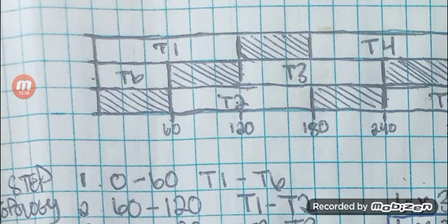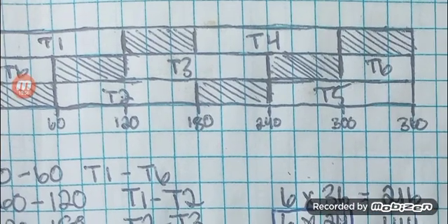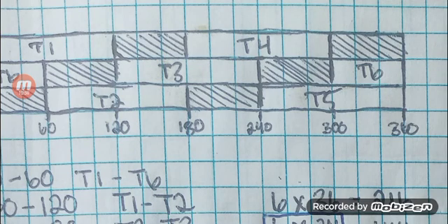And T2 turns off, T3 stays on, T4 comes on until 240 degrees, and then T3 turns off, T5 turns on till 300 degrees, then T4 turns off, and then T5 stays on, T6 comes on till 360 degrees, and it starts over. And that's per cycle, per 360 degrees of rotation of the motor.